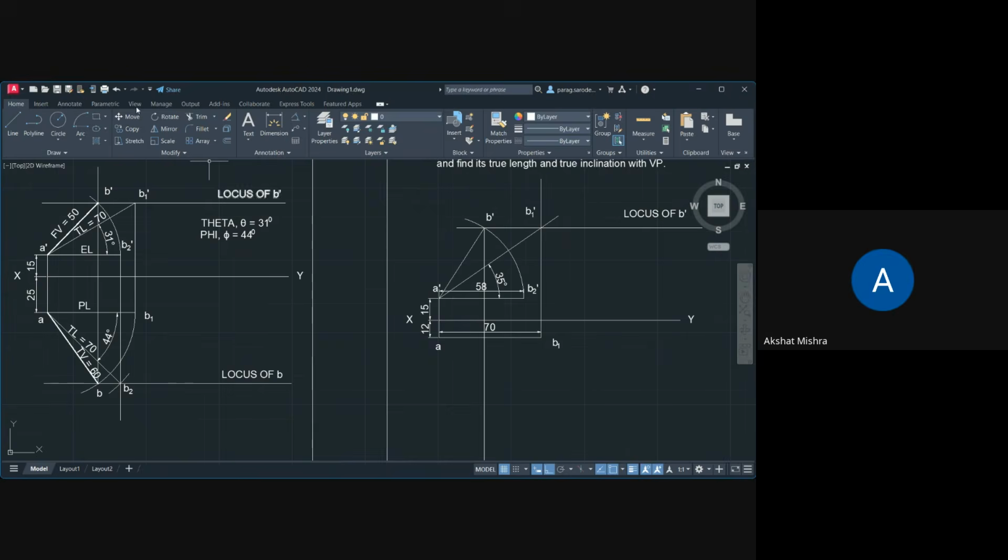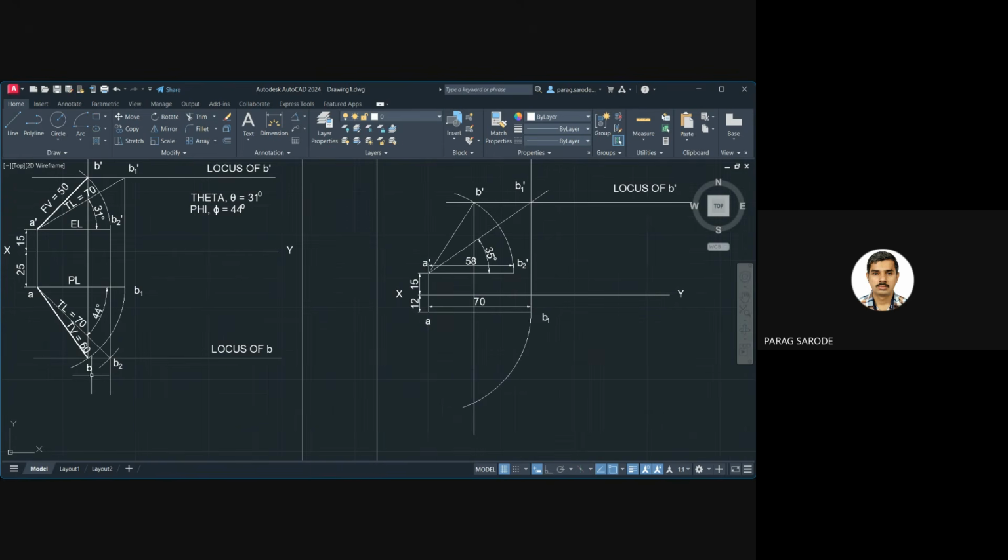Yes, sir. We'll take that. Center, start, end: center is A, radius is B1. Now arc always starts anti-clockwise, so we'll press the keyboard control, and you can see this. If I press the ortho off, then I can make the angle less than 90 degrees also, like this. Okay. So what is this point? This point is B. Okay.